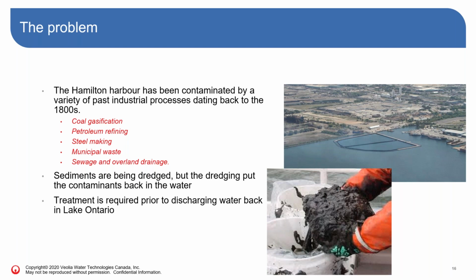But as you dredge, if you're familiar with it, dredging is kind of a vacuum system. You're sucking the sludge out, but when you do that, you actually entrain a lot of water with it. That water obviously picks up some of the contaminants. We need to treat that water before we discharge back into Lake Ontario. So that's what we've been hired to do.